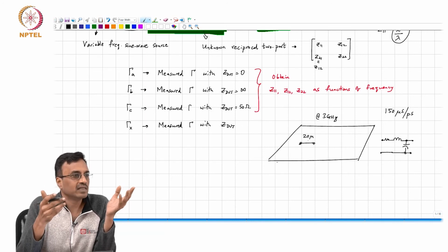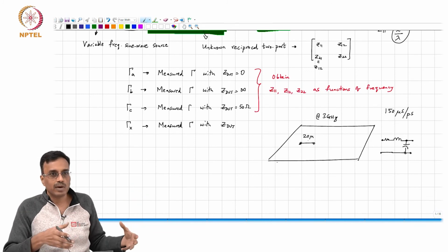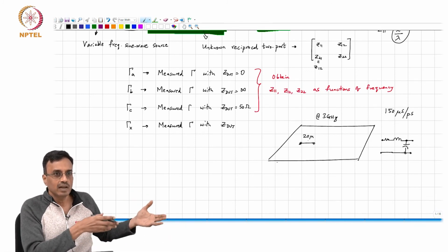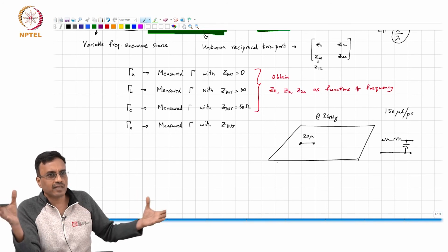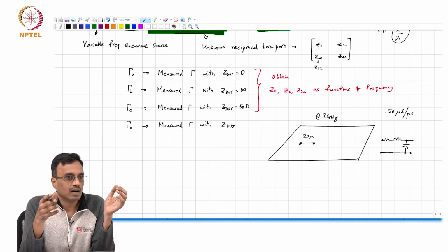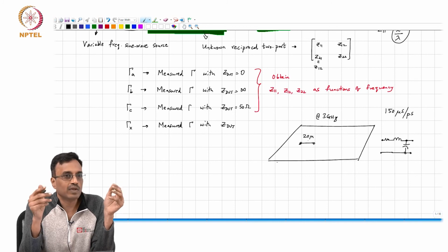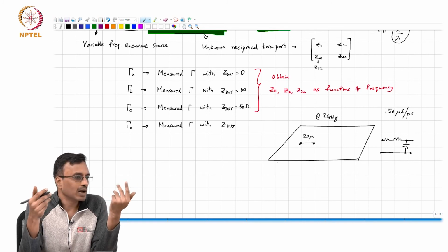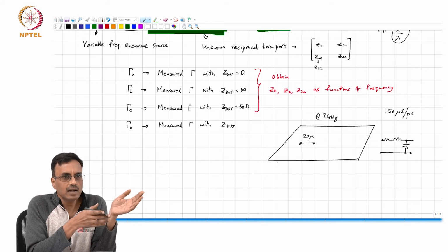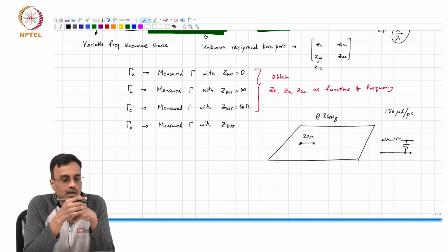So on an IC, the absolute frequency of 3 gigahertz is of no fundamental consequence, right? It's as easy or as difficult as assembling things on a breadboard at a much lower frequency, because on a breadboard all physical distances are much larger, and therefore what constitutes a high frequency on a breadboard is in absolute numbers much lower than what constitutes high frequency on an IC chip, right?